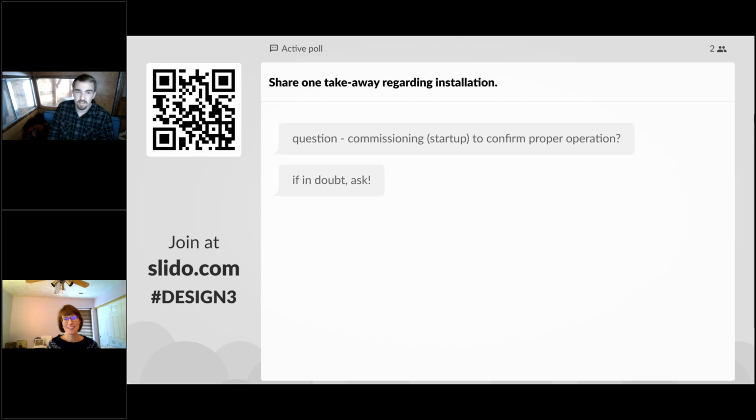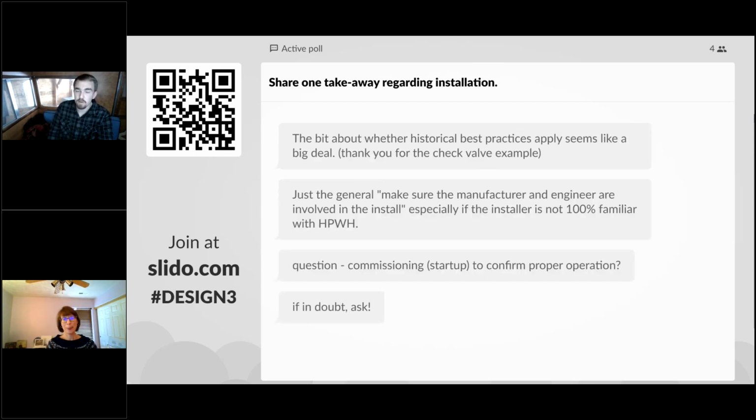But once you have to remove that check valve, that means draining the entire system and cutting the piping open and then getting any copper remnants out afterwards. So it's a big issue actually removing it. And then the second most common thing I would say is the placement of these sensors.